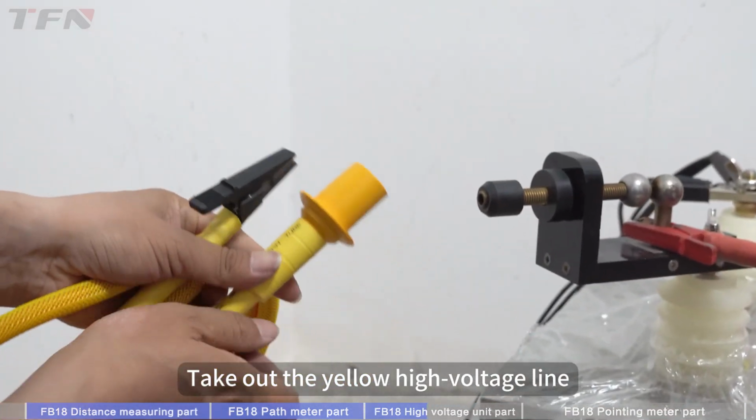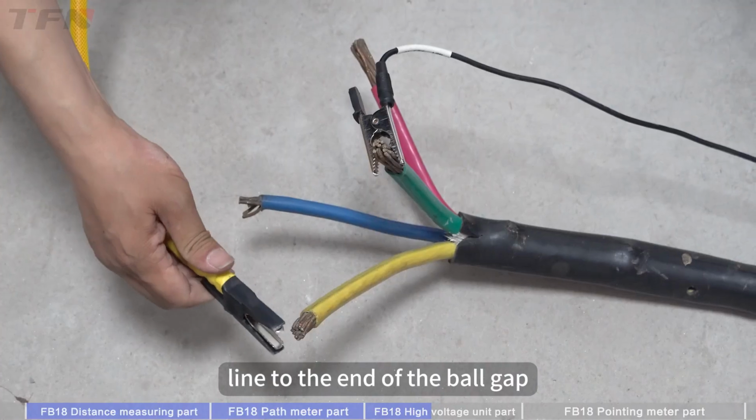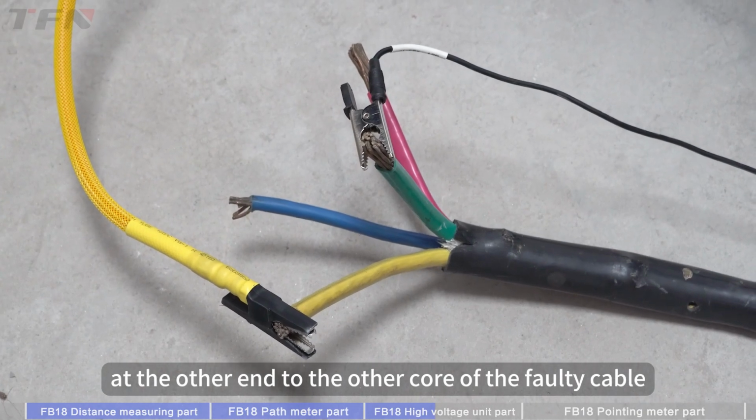Take out the yellow high voltage line. Connect one end of the high voltage line to the ball gap and connect the alligator clip at the other end to the other core of the faulty cable.